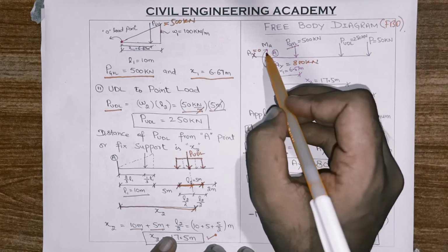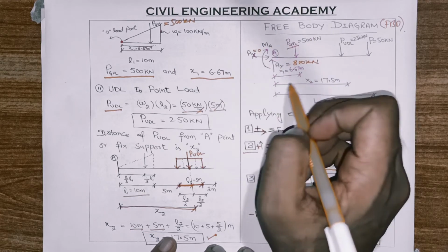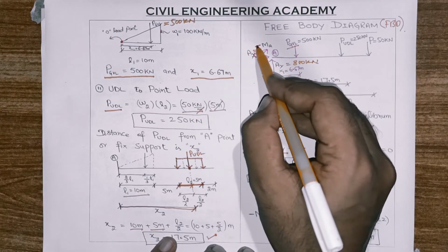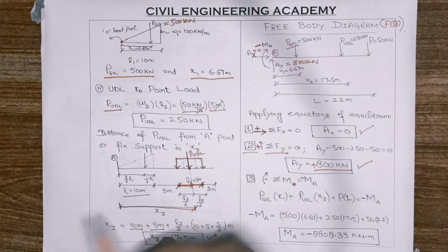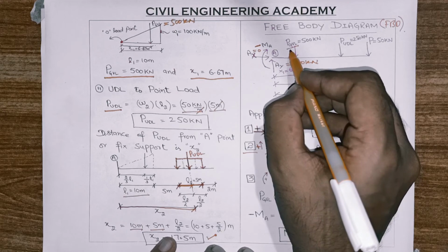So the last thing which remains is MA. Because this MA is acting in the clockwise direction, it will be treated as negative, and anti-clockwise or counterclockwise moments are taken as positive.